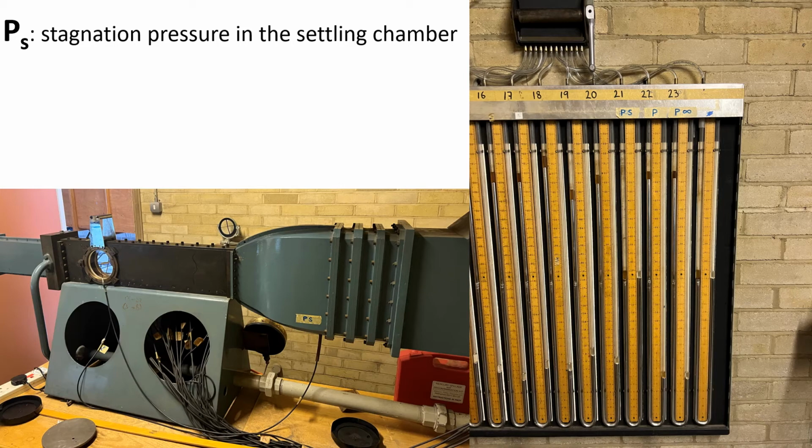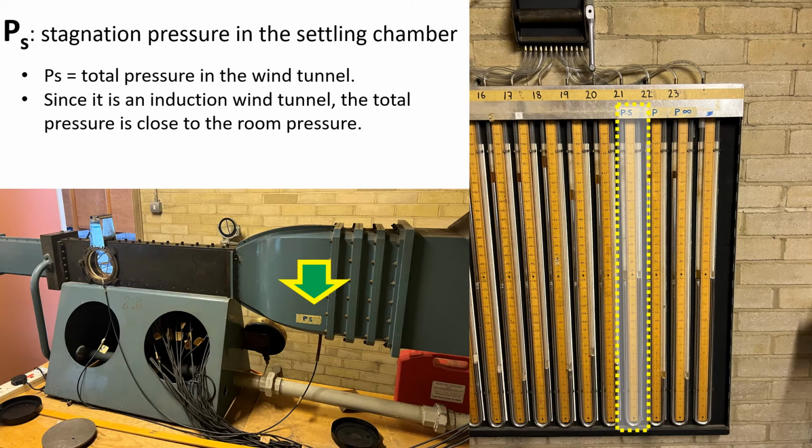So in the experiment, we are going to take 3 readings. The first is PS, it's called stagnation pressure, and the measurement is inside the settling chamber as highlighted in here. Accordingly, it's number 21 of the manometer. So PS is the total pressure in the wind tunnel. Because this is an induction type wind tunnel, the total pressure should be very close to the room pressure. So the total pressure is not so high.